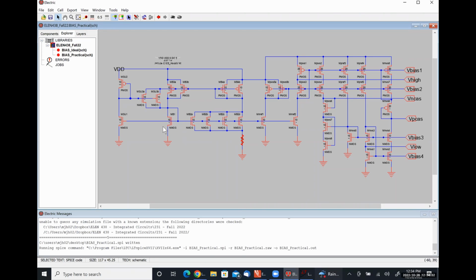We just found the current that's flowing through this particular NMOS transistor. Hopefully everybody on Zoom is paying enough attention to see what I'm doing. We found the current through this one right here. This one is supposed to be a copy of it, because it serves as the reference current for the long transistor of the wide swing current mirror. This one is another important one because it serves as the reference current for the cascode portion of the wide swing current mirror.